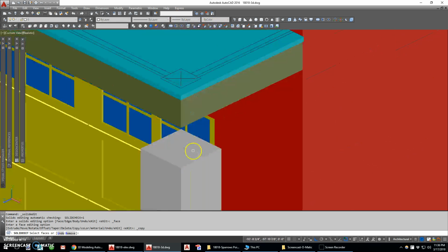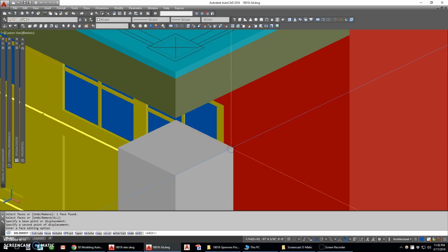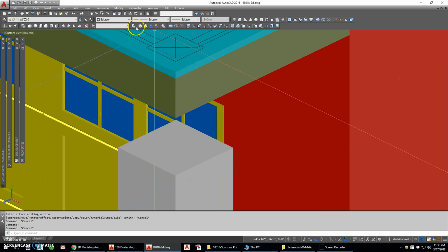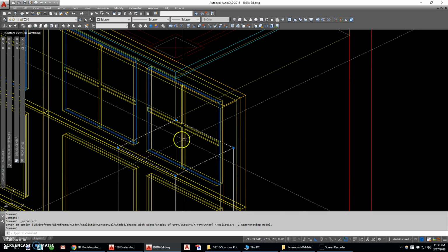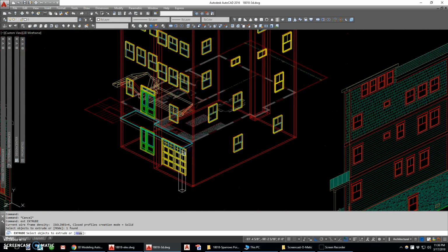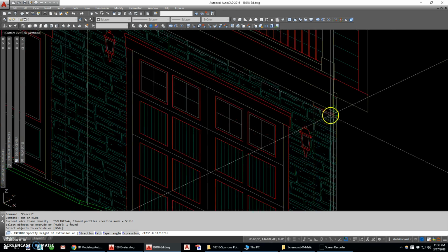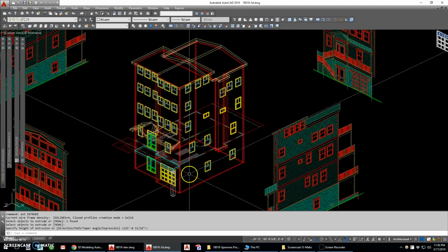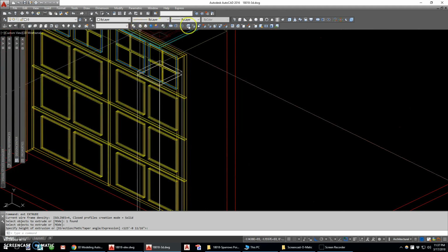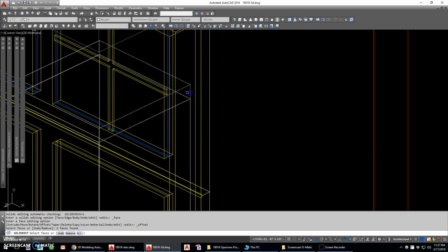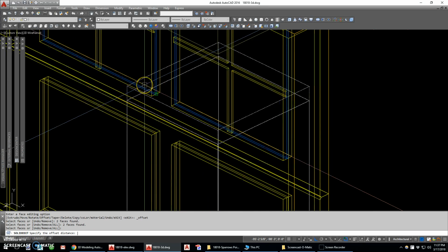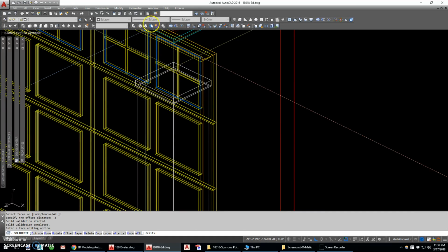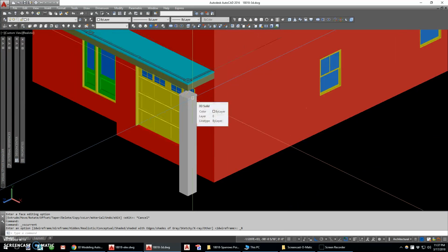So again, I'm going to use this copy face command. I'm going to copy that. And you can't see it, but there's another object there. If I go into my wireframe, maybe I can pick it. Okay, that's my region. I'm actually going to extrude that, and I'm going to use my elevation as a reference, probably 2 inches or whatever. That's probably another 1/2 inch overhang. So what I'm going to do is go into my offset faces. I'm going to click this and this and say 0.5. That kind of gave me a cap. So I've sort of got that column done.